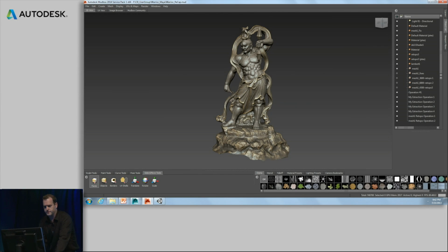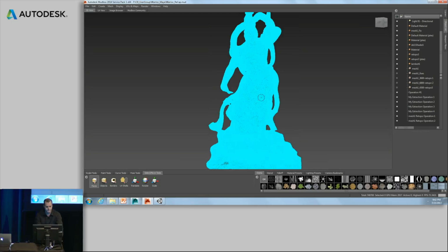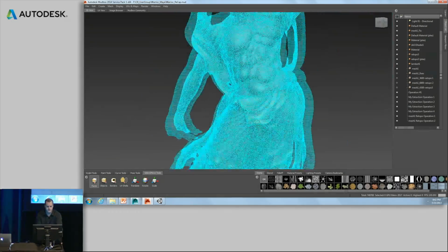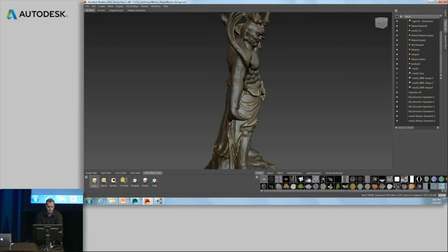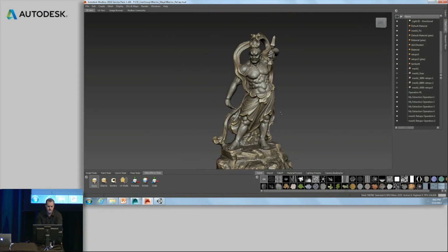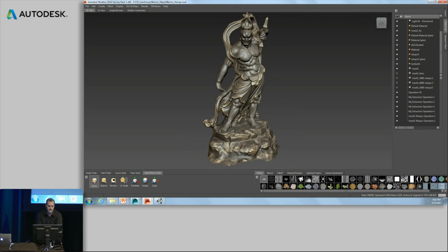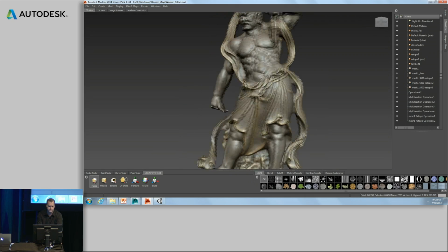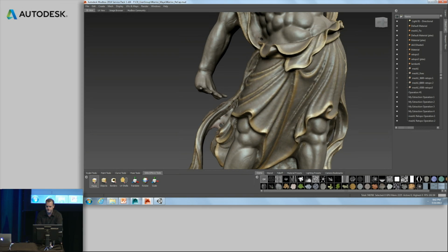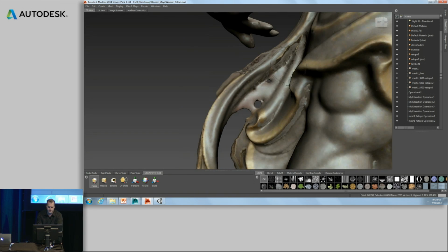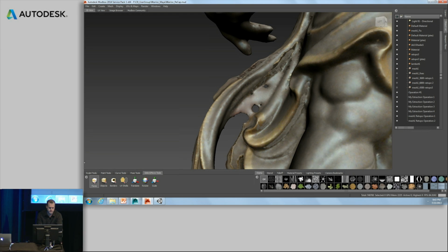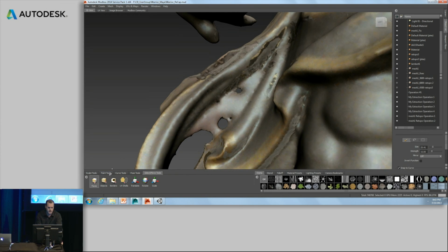And this is the mesh as it actually came right out of Recap. So if I put this in wireframe and take a look, you can see it's a very dense triangulated mesh. But it's done a really nice job here. If we tumble around and take a look, that's not bad for a series of photographs generating a mesh from a real-world object. But with photography techniques, some of the things that we can sometimes notice are areas where the texture may be mixed up a bit, or unwanted holes, things that are culled out by the actual capturing technique. Not a problem.